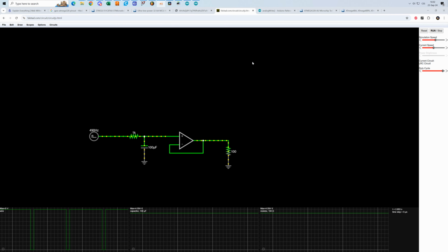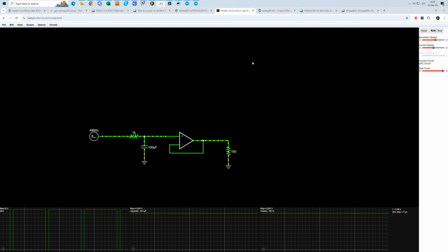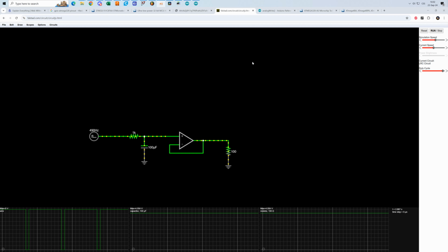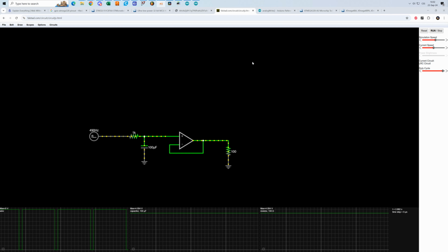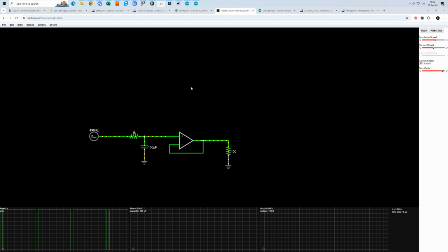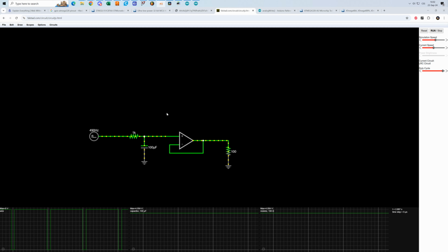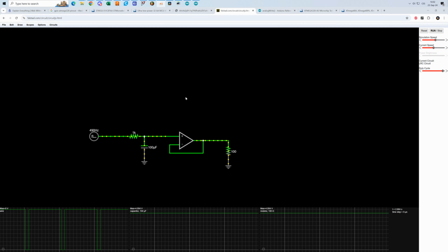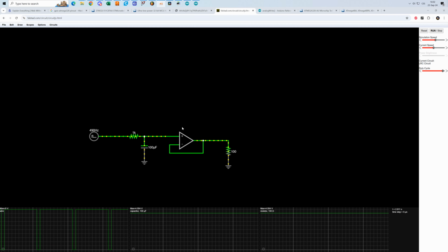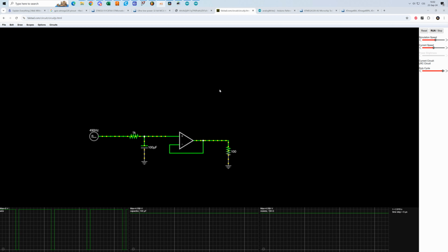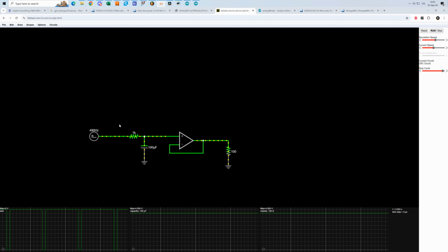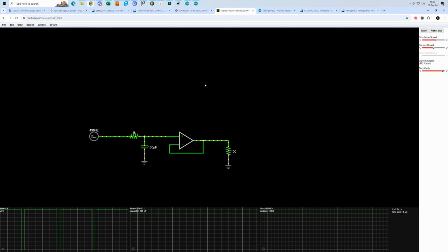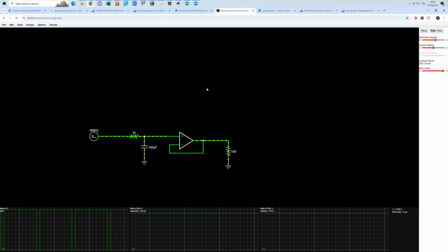Of course, you cannot expect much of this circuit because there are two big limitations. First of all, the PWM has some resolution, so it cannot output just any duty cycle. There are smallest possible changes of duty cycle which depend on the resolution, and the resolution of the PWM on the Arduino is not very great.